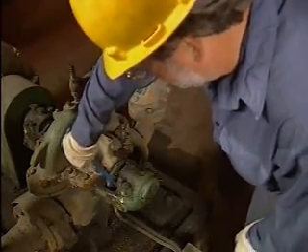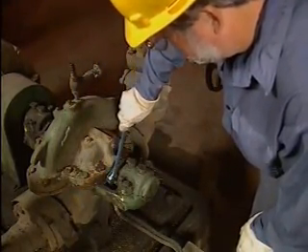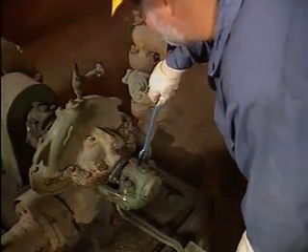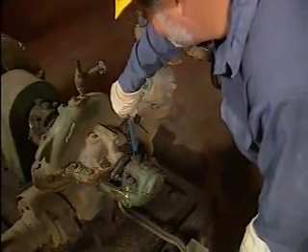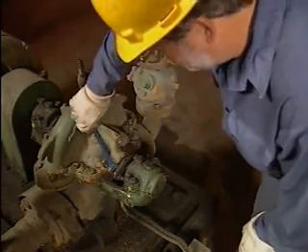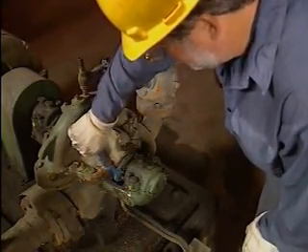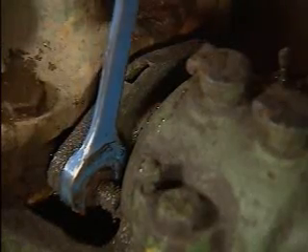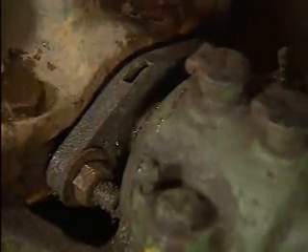Over time, the gland follower can be tightened to compress the packing until almost all of the lubricant is squeezed out. As lubricant is released, the packing shrinks to a point where it can no longer be compressed to effectively control leak-off. When this happens, the packing should be replaced.